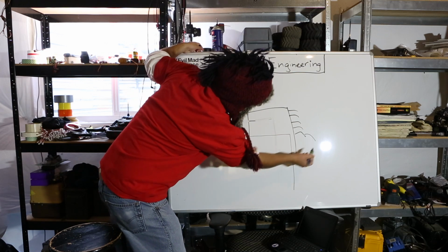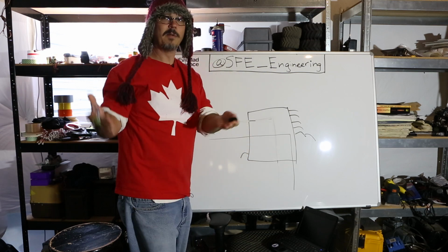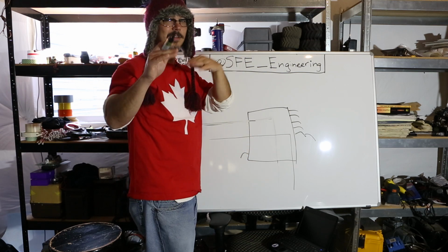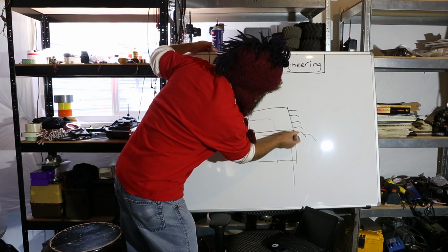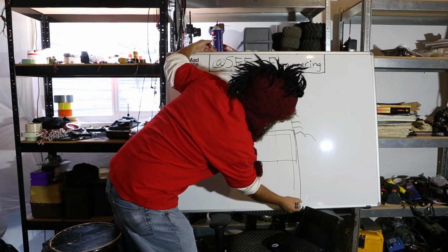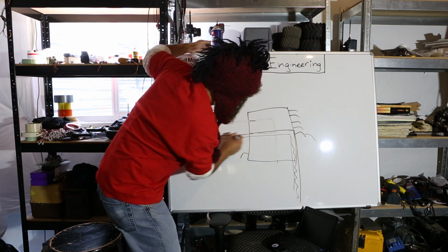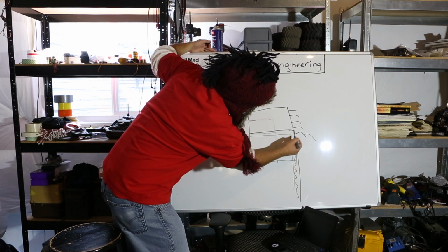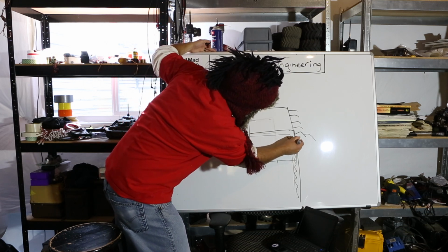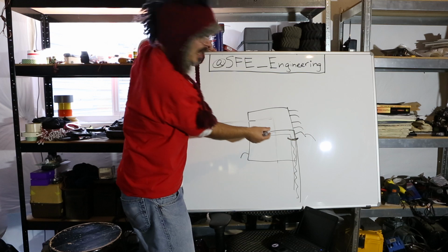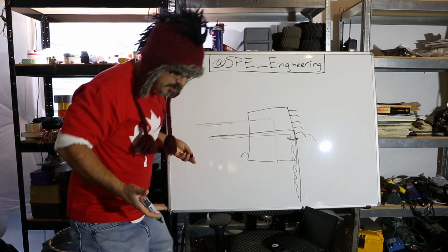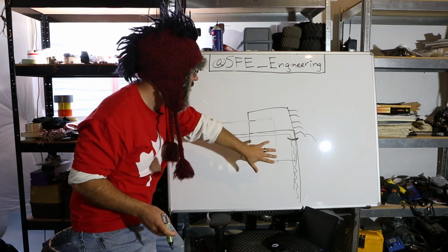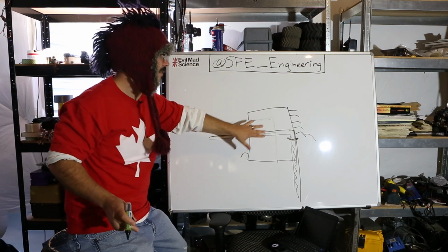And then what they will say is connect the digital and analog ground in only one place. So you will have two different ground planes that run sort of like this, and this is empty space in the copper, okay? And then you make one connection between the two copper planes on the bottom side, okay? And the reason they do this is to keep noise out of the analog section, right?